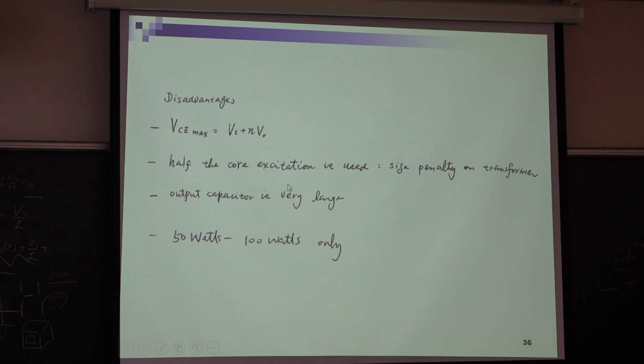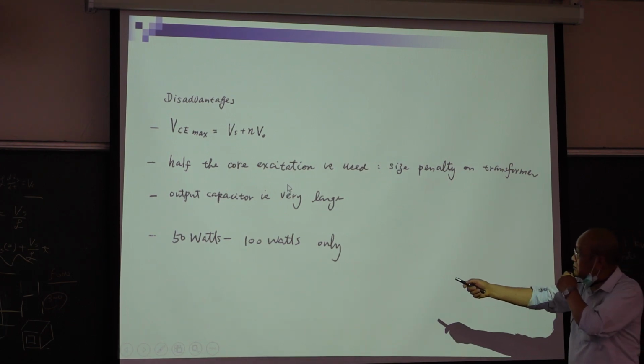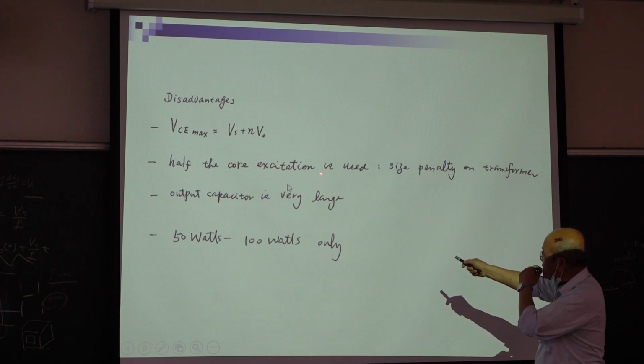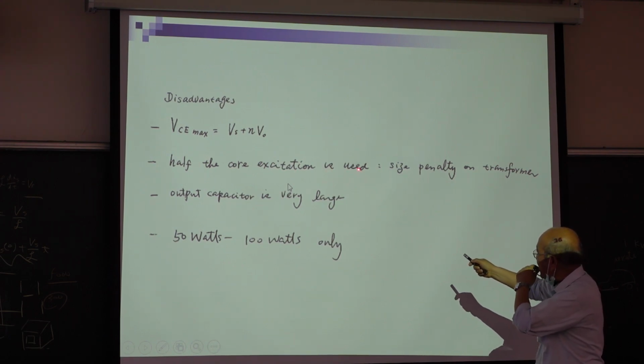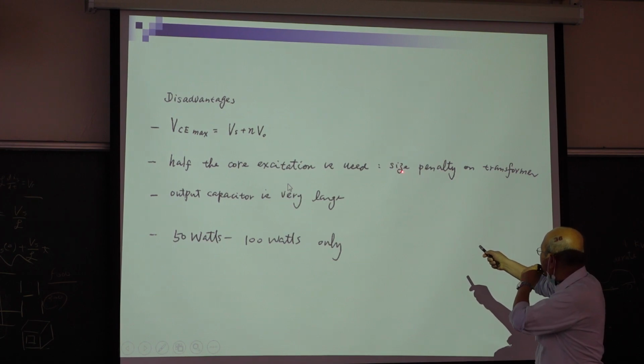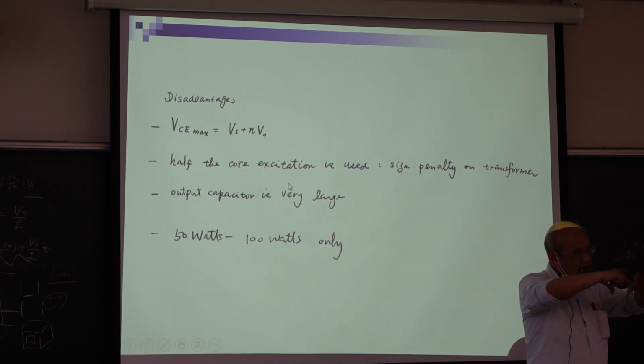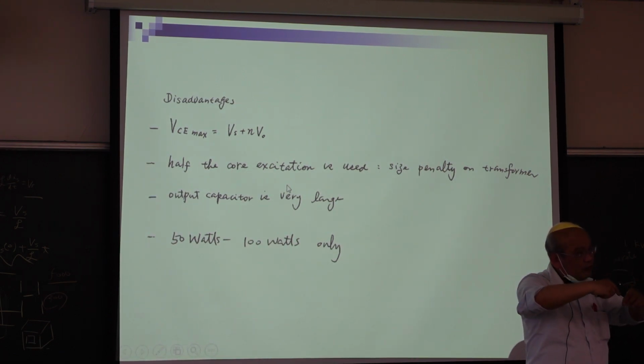So if you are very healthy, you say, oh, I can work 10 hours a day. If you are sick, can you work 10 hours per day? No, you can only work 2 hours a day. So you have to do what? Derate, right? We have to derate because we use this not as a transformer. We use this like a coil. So we have a size penalty, which means originally the transformer is high power, but I cannot use full power.